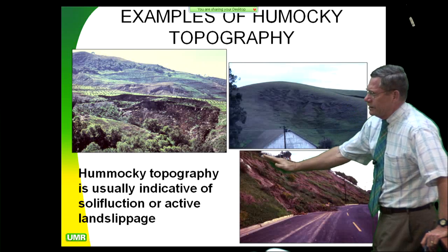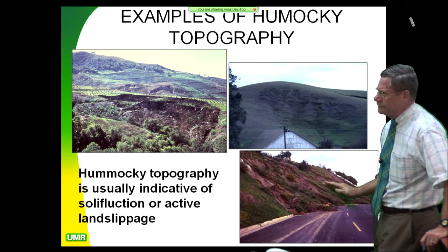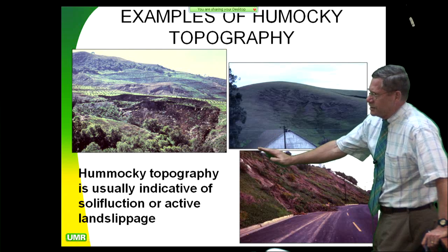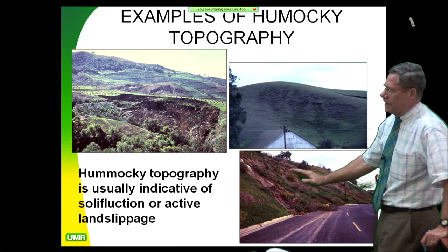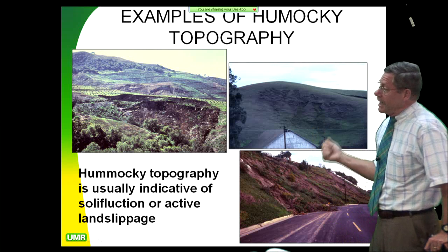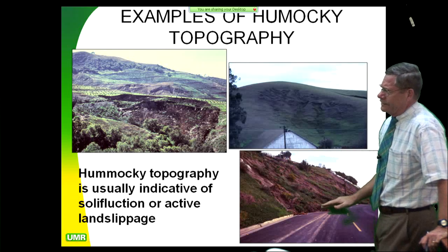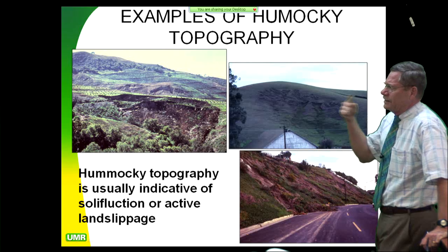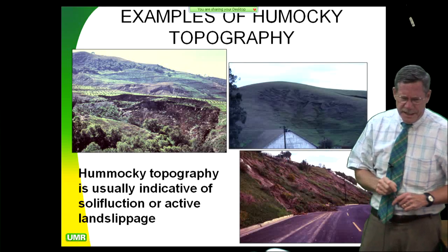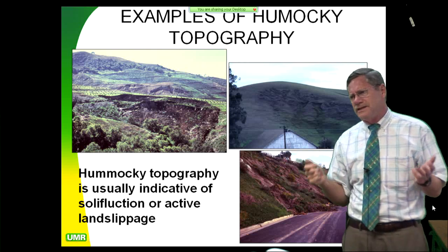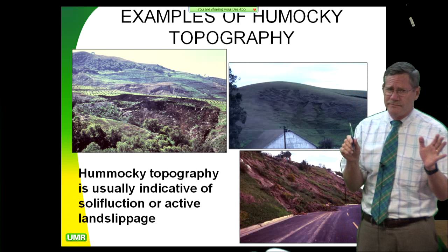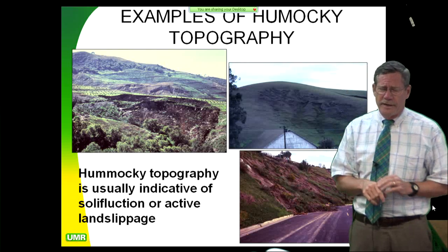Here's a typical cut slope failure down in Orange County, where the upper 60 centimeters to 100 centimeters has just come off the slope. And what keeps all these slopes in place is negative pore pressures. When they get saturated, they come down. They don't get saturated very often because it takes a lot of moisture over a long period of time. And what you learn about this stuff is it isn't the big storms that get on the 6 o'clock news that foment anything but debris flows. Those foment debris flows. We're going to talk about debris flows.